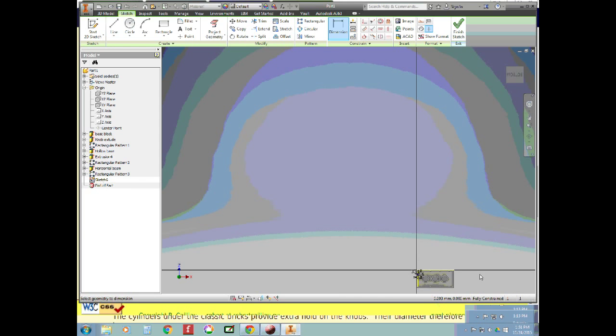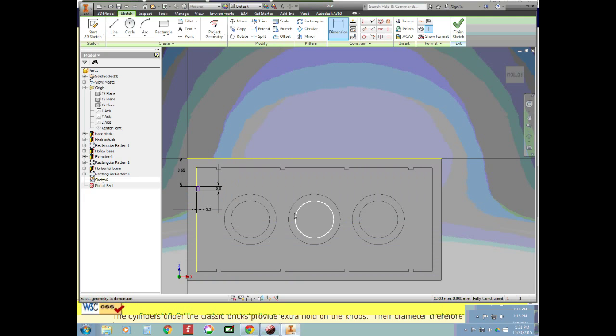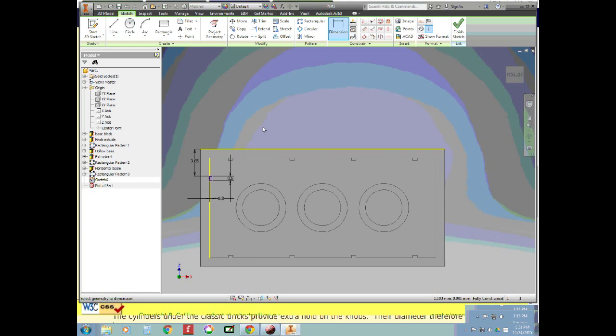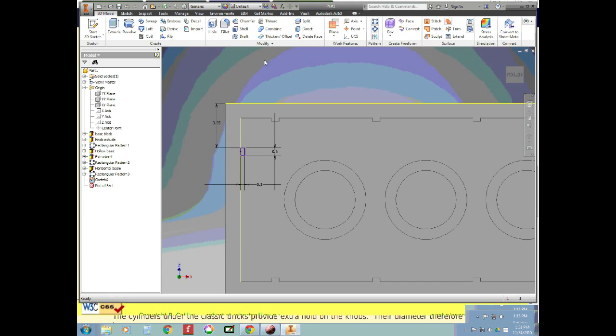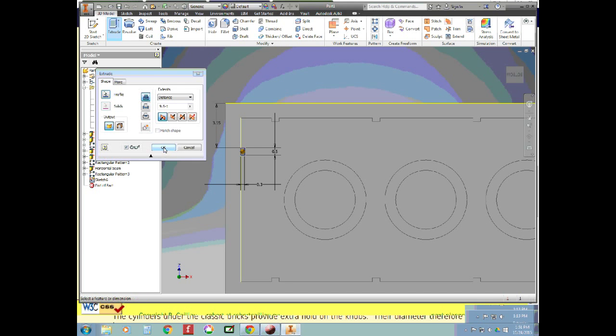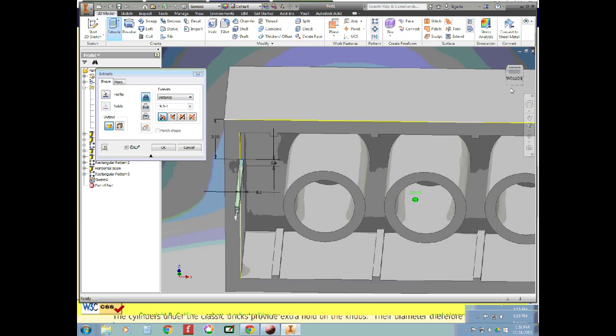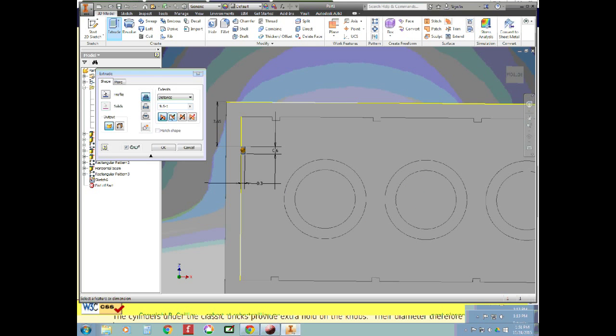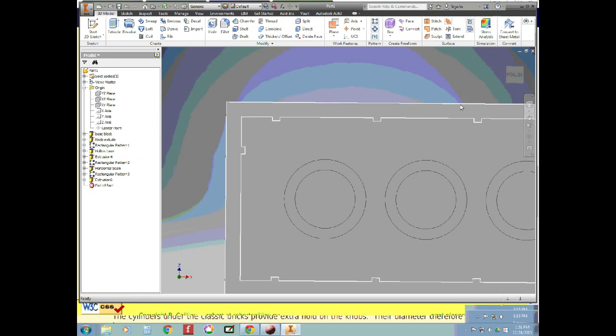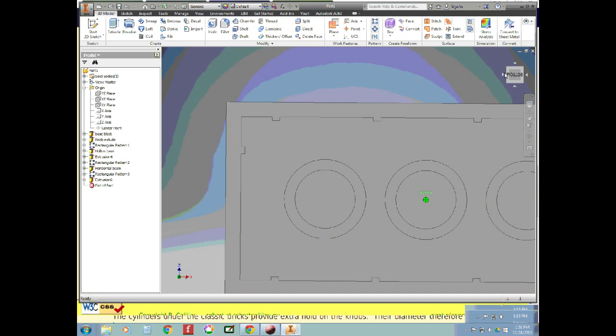So we're now ready to extrude this and then make the pattern, and then this brick is done. So right click, and again I can get out of the dimension tool and finish my 2D sketch in the same step. And right click and choose extrude. It has my geometry selected, but again it's the wrong direction, so we want to go back and click OK. And there is one of my vertical beams.